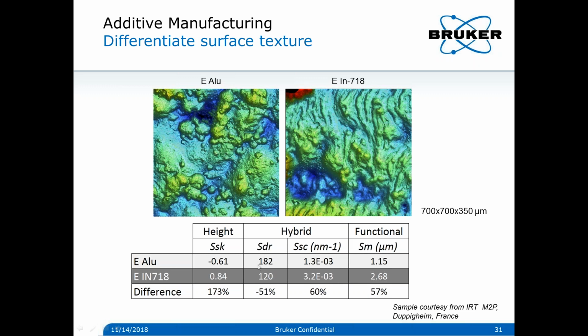The same applies in terms of SDR. It tells how much developed area we have, and whether we'll have an issue further on in terms of painting, for instance, the ability for the paint to anchor or not on that surface. So all that will couple back to fine-tuning the parameters, and also to understanding whether the surface needs further sandblasting or further processing in order to comply with the use or the next process steps, such as painting and coatings.